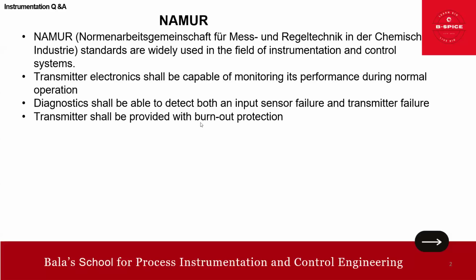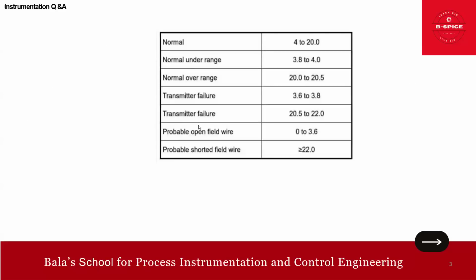For example, pertinent to this burnout protection, if we talk about a Yokogawa transmitter, at the end of the model code you have a slash C1 or C2: burnout protection up direction or low direction. So that feature is there. This is a summary. Now I'll dive deep into this so that you will get more. Now I'm going to talk about NAMUR NE43.